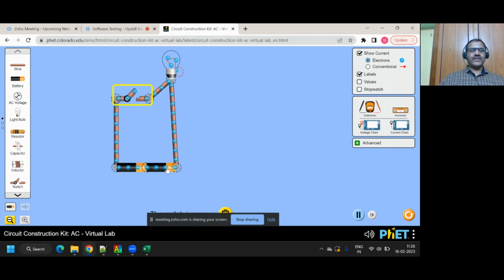Why? This is short circuited because the bulb has 2 points. One end should go to one end of the bulb, the other end should go to the other end of the bulb. In the battery lights, you could have seen that. This portion is connected to one end, there will be another knob connecting to the other end. Now I connect that way because I missed that step. In the procedure, I connected both the ends of the wire in the same way. That I should not have done.